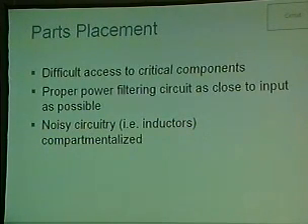So also proper power filtering and the noisy circuitry, that's also part of noise. The reason you want to reduce the noise issues is because there are some attacks, such as Tempest, which we'll touch on also later, that make use of the stray noise generated by the device. You could possibly recreate images from a monitor or gain secrets or private data. So you want to keep the noise down also for FCC regulations, and if you're doing medical devices, FDA regulations, you need to keep the noise down. And that's just a good design practice.